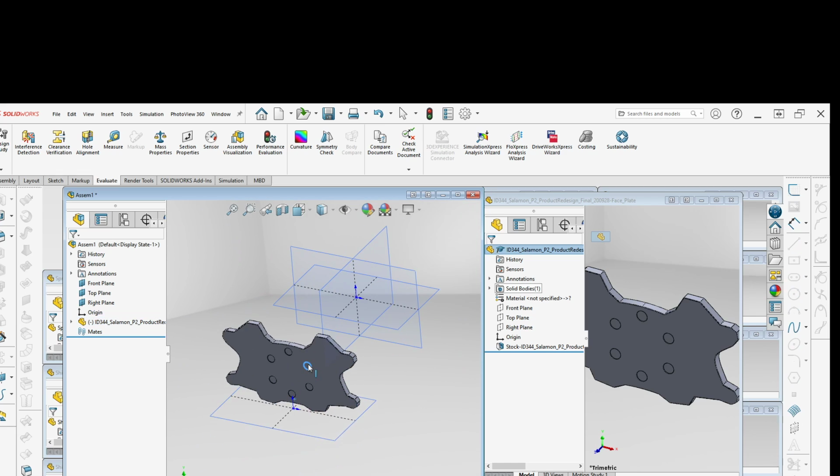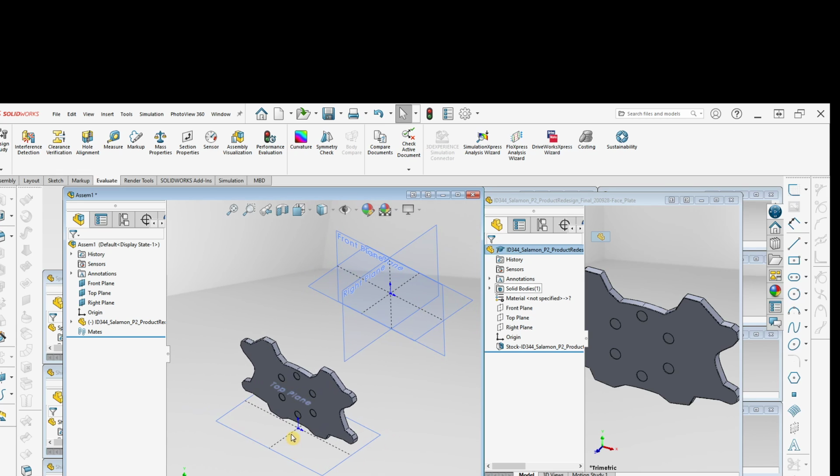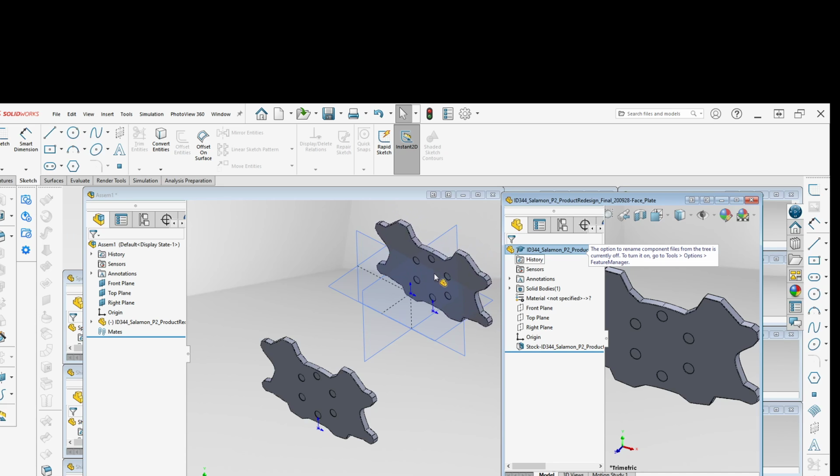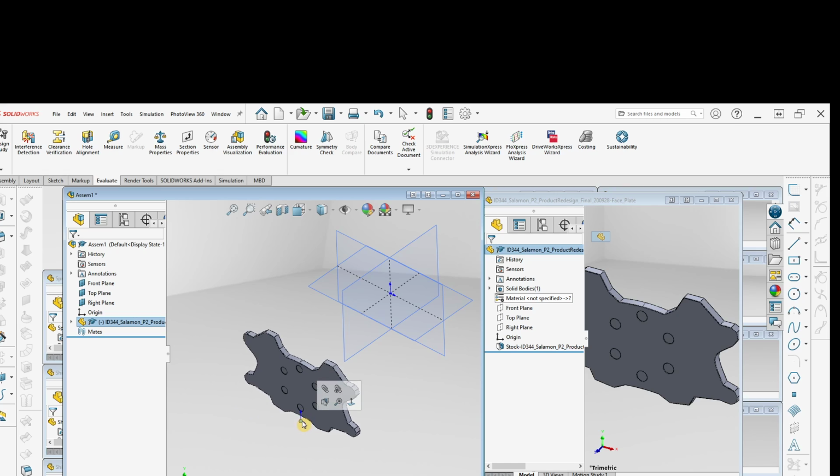And from there, I would ideally have to put it in the proper space that it was built on. If I took all my time to build my original model around the origin, then I want to get it back there. So for this, I would most likely have to take this plane, align it with this plane, and do a variety of other things to get it in its perfect spot. Now, if I come in and drag it, and I place it over top of the origin, you can see that it automatically snaps. So let me just do that again. If I click on here, you can see there's an origin for this part.